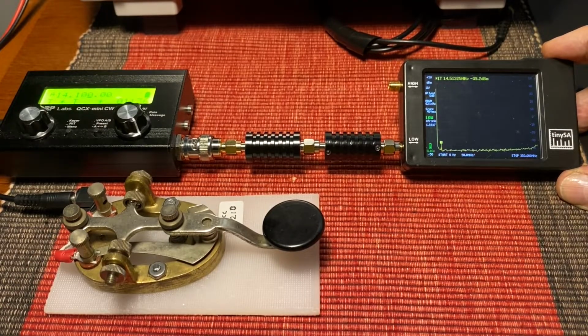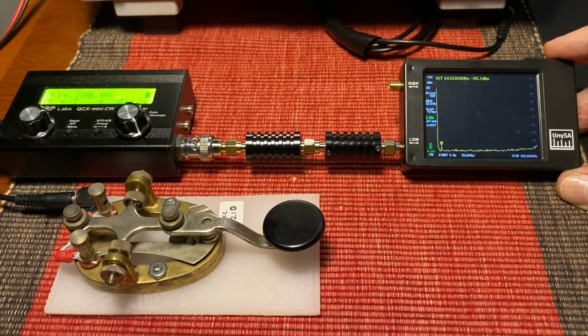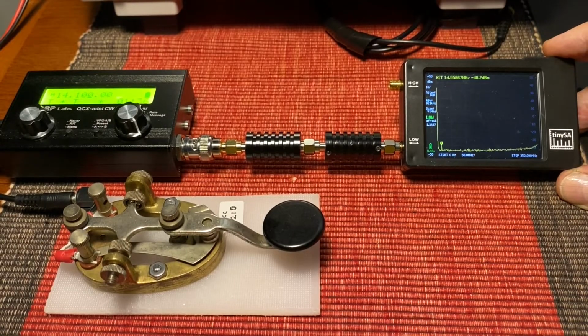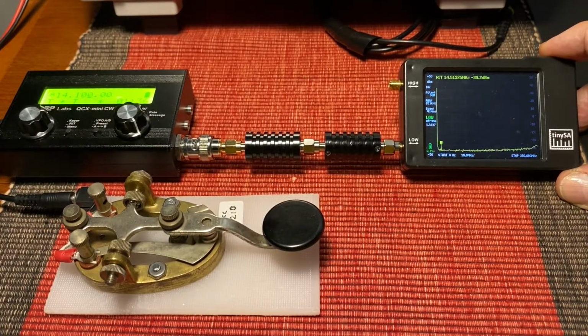First, I'm showing you the setup that we need to drive it. We have to protect its input because it can't withstand very strong signals. So I'm using two 20 decibel 10 watt attenuators in line between the transmitter and it. They're also functioning as dummy loads. I'm now going to switch over to a closer display of the TinySA, and to do that I'll have to stop the video for a moment.